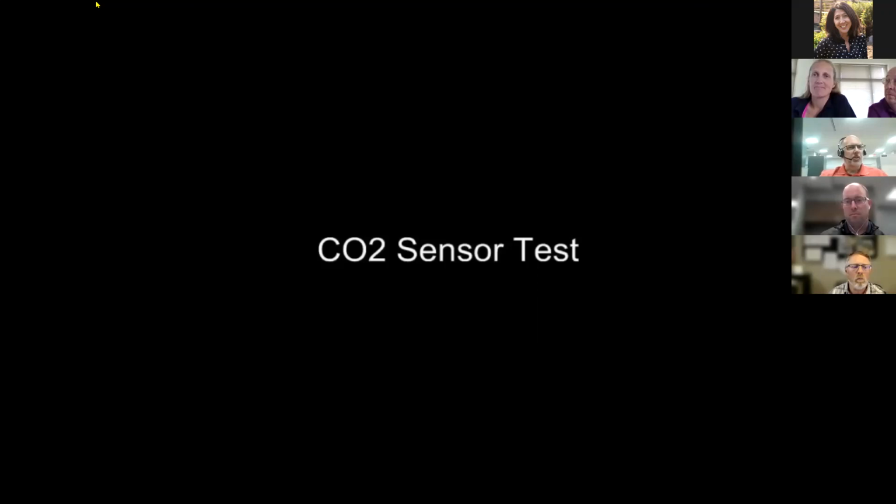Well, I think you partially answered the question. Are there any practical ways you know of to trip the duct detector at the device rather than with the test switch? Well, there's also a magnet typically. A magnet kind of does the same thing as the key switch. And I guess there's also pulling the relay. Well, that would demonstrate the wiring part of it on the controls. Right.